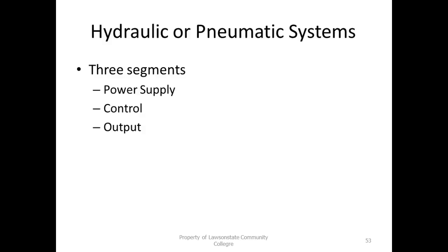And then a gas, we have to pressurize it before we use it, right? So we understand the difference. In pneumatics, before we can use it, we have to generate a pressure. So that's what a compressor does. A compressor generates a gas pressure, and then of course a liquid, all we have to do is push it against something.